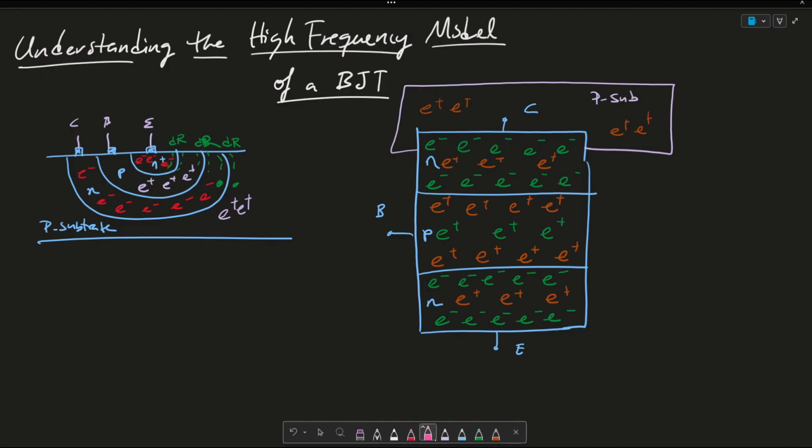So another way to think about this is by looking at this model that's located here. And essentially, every time you have a PN junction, there is a parasitic capacitance. So for example, in my NPN, I'm going to start at this first N. There's going to be a PN junction that looks like this. Okay, so N here and P. And whenever you have a junction, there's something called a junction capacitance or a depletion capacitance, which is parasitic, right, in this depletion region. So in this situation, we're going to call this the parasitic capacitance at junction C or junction collector. And then again here, if you notice, there's another depletion region where, again, this is PN. So there's a parasitic capacitance at the junction of the emitter.